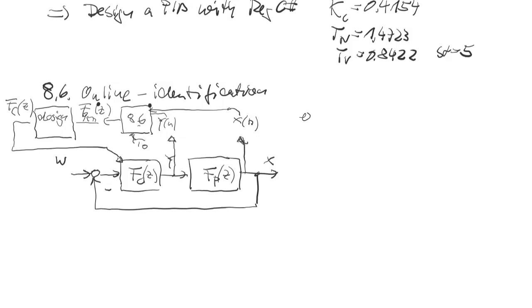This is called an online adaptive system. Adaptive means that if there is a change of signals, or a change of model parameters, say the K goes up and down, or the time constants of my process go up and down, then automatically these changes are sampled and used for a new identification, for an actualization of the process model.